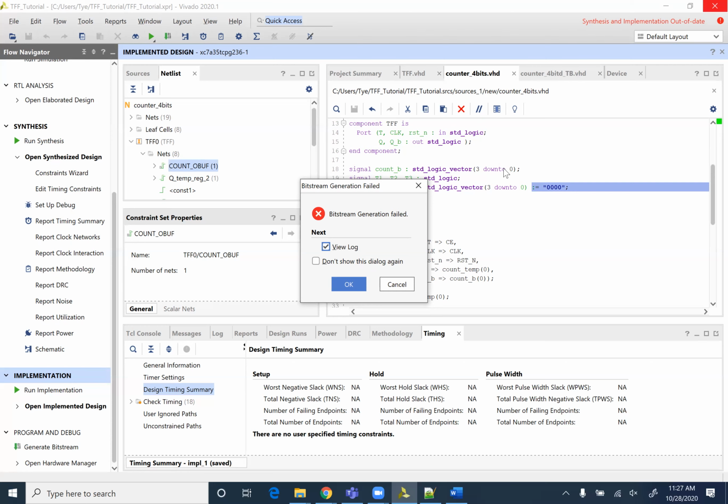Yeah, but realistically, there are still what we call CPLDs, complex PLDs, that are also reprogrammable. They're less user-friendly to reprogram, but they do retain their information on power down. These tend to be smaller, less customizable, and much cheaper. And you will encounter them in industry if you ever go into manufacturing design. If you're building industrial machines, CPLDs are prolific.